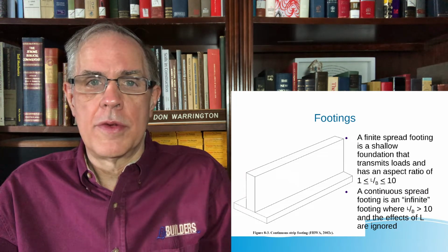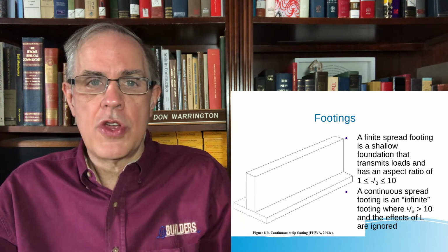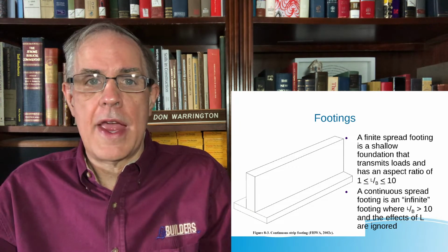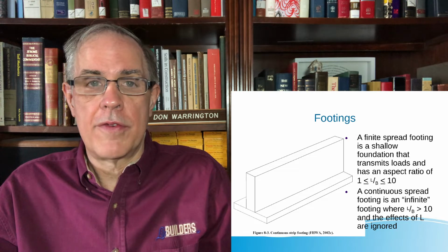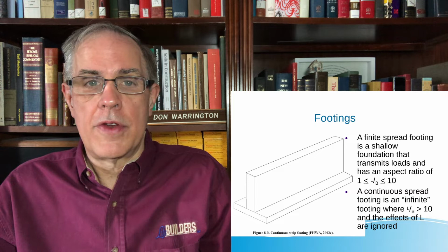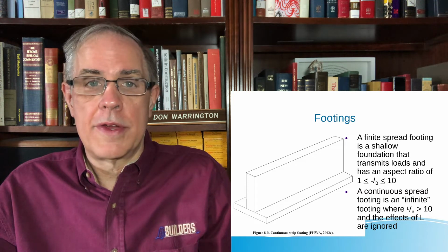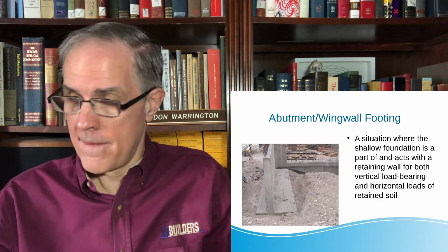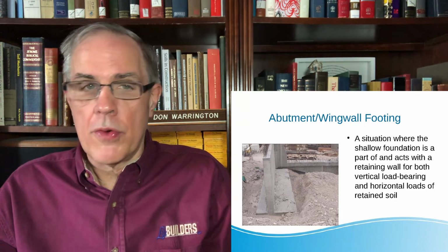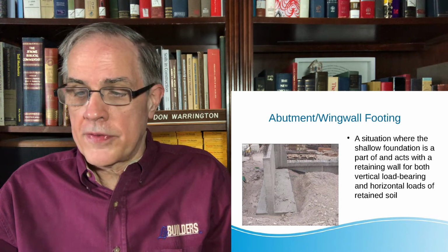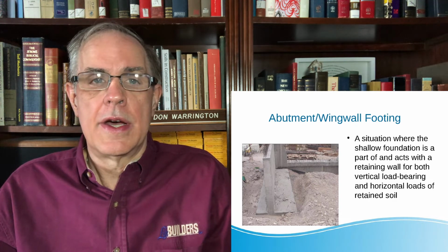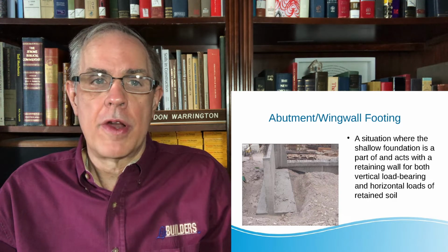It's important because it allows us to use continuous footings and infinite footings as a practical design tool, and frequently it's very useful, particularly in footings along retaining walls and slopes and that sort of thing. An example is an abutment or a wing wall footing where the shallow foundation is a part of an axis of retaining wall. In other words, the shallow foundation is part of the retaining wall.